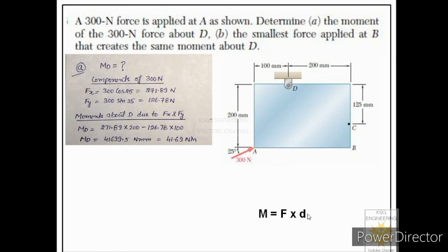So let us see how we can increase the moment arm to maximum when we apply force at point B. So let us first connect these 2 points, OB, and this is the moment arm, I should say, if we want to apply force at B and keep that force minimum, because for minimum force we need maximum moment arm.